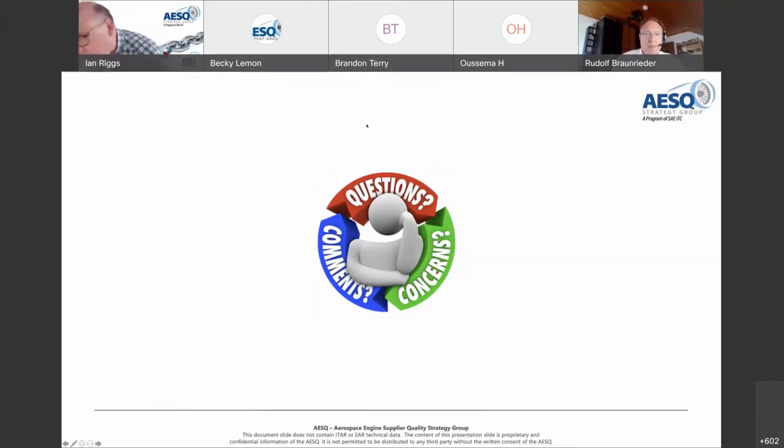So it's kind of hard to be definitive without the example, but potentially the answer to that is yes, because that change on product A may have a different effect, may have a different occurrence to something on product B. So as we talked about yesterday, an FMEA should be applied to an individual part number, because the way parts are used in the final product can be very different.